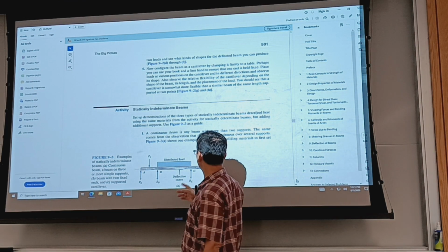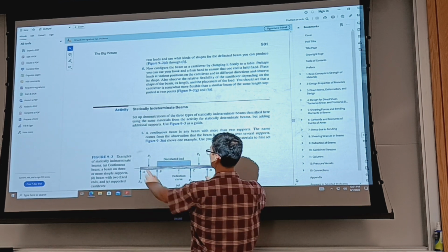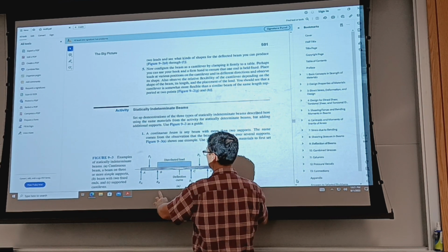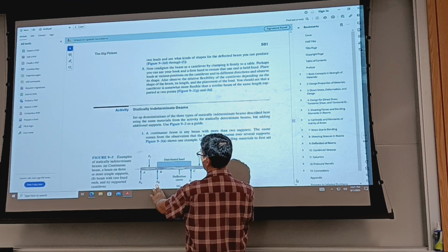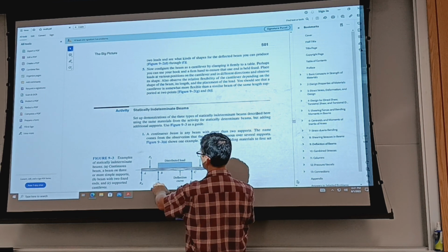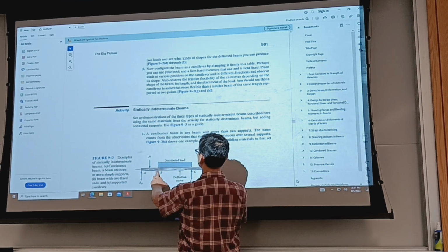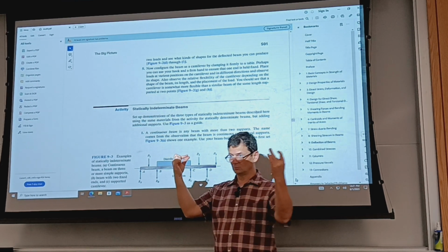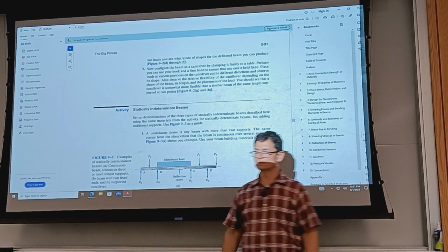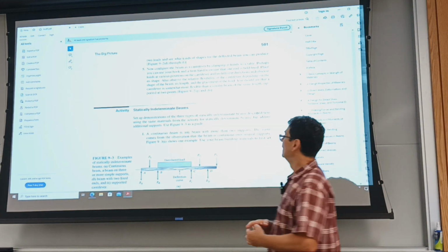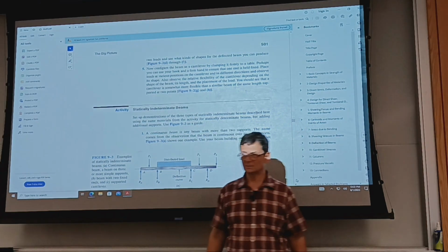So if I have, well, here there are four, but if I have just two supports, and I'm assuming the live load, and if I'm assuming additional loads that are unknown in magnitude, but I manipulate them until the deflection where the two additional supports are goes to 0, then I am capturing this statically indeterminate case using simply supported cases. Does it make sense?